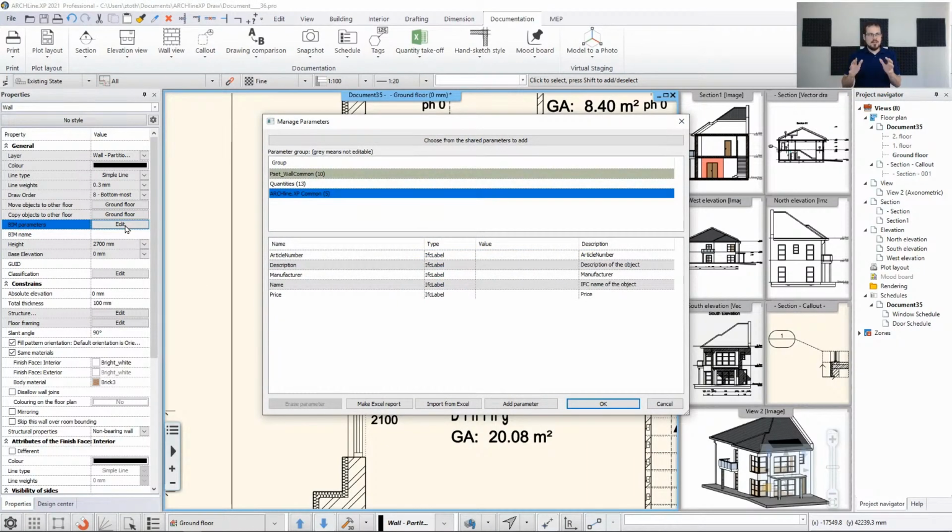So whenever you have an item, any kind of item, doors, windows, objects, roof layers, etc., then this is where you can add information bits, additional data fields, which would be the building block of building information modeling. And later on, when you're making an export, either into IFC or into an Excel, these information bits would be retrievable. That's just a short detour. But if you ever want to work in BIM, then you need to know that the basic building block is information, and this is where it is stored in ARCHLine.